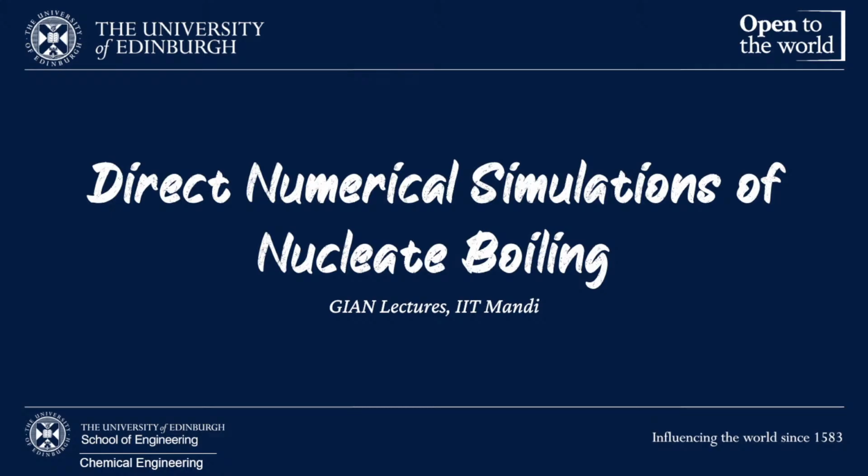Evaporation occurs at any temperature, but boiling occurs at... What is the thermodynamic difference between the two? We talked about VLE, vapor liquid equilibrium. So evaporation is a slow phenomenon, but boiling is a very fast phenomenon. It's a non-equilibrium thermodynamics. So essentially your phase change model is completely different in boiling. When you have evaporation, you are at the mercy of vapor liquid equilibrium thermodynamics. Here you don't have that time at all.